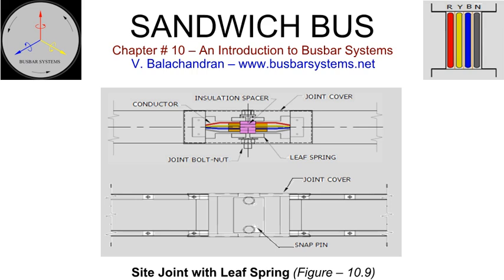In a busway, the joint temperature is the hot spot and therefore the joint must be monitored for low contact resistance. The conductor joint bolt must be torqued to the desired value. To ensure the same, all busway manufacturers install a double-headed bolt at the joint. The bolt is tightened holding the top head till it gets sheared, an indication that the desired torque has been achieved.